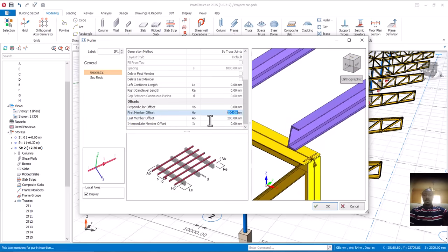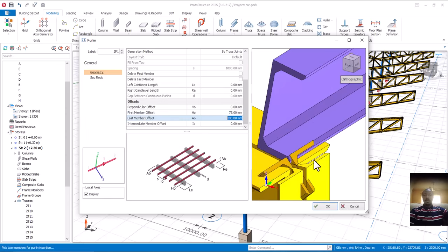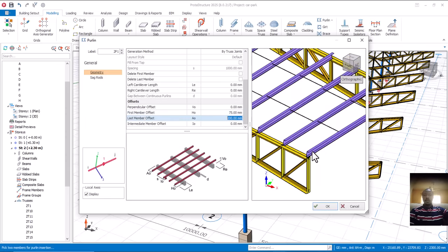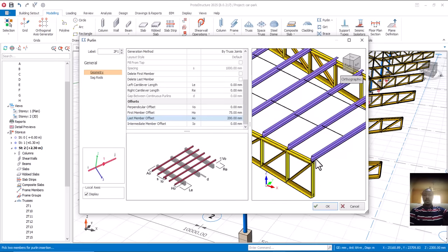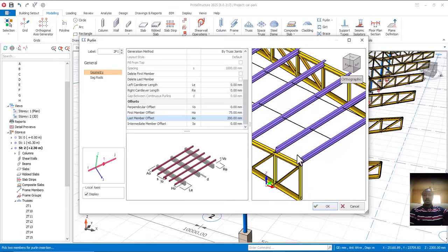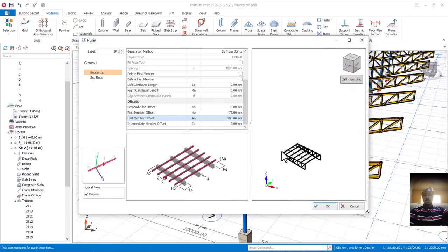So that's why if I shift it like this, 75, can you see now, very at the edge. So if you now have maybe 25 mm or 50 mm projection, it's not bad, it's still okay. It will have enough strength to withstand the wind. Is that okay? So the same thing happens to the other side.